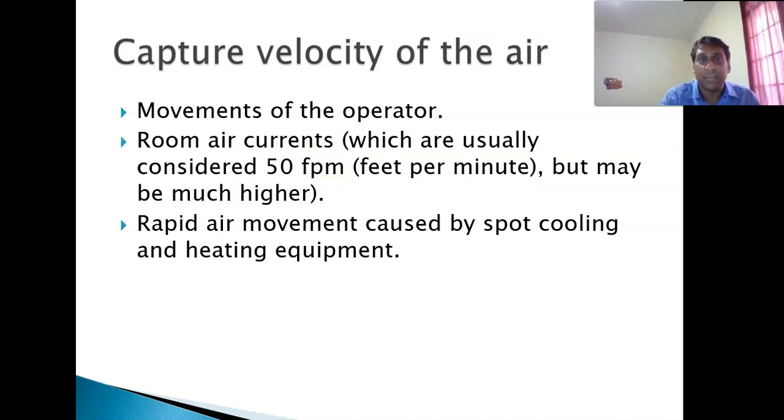So quite a nice concept here if you got it, that the capture velocity has to be greater than all of these competing systems for the contaminants, so that the capture velocity must be large enough to overcome all of these competitors anyway, to get the contaminant into the duct of the LEV system. So I guess a graphical representation here.